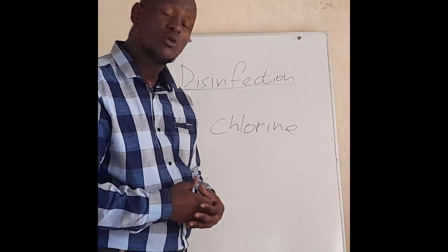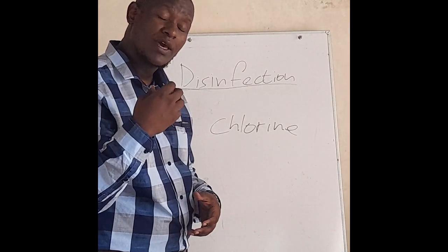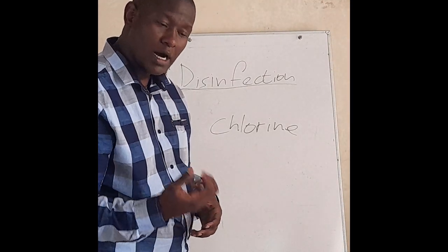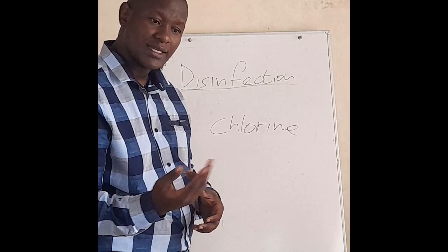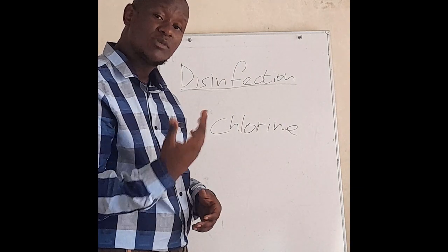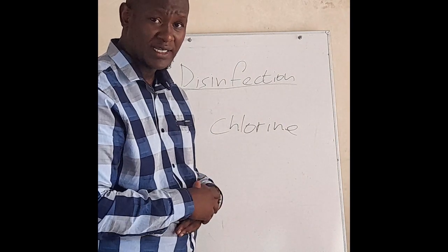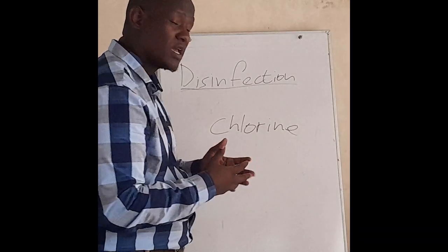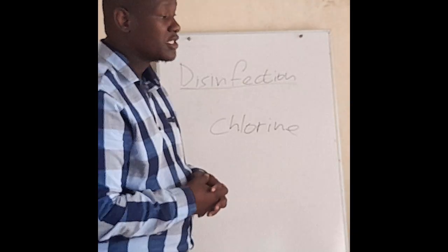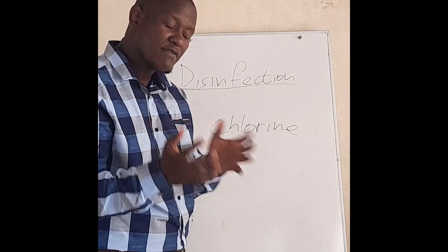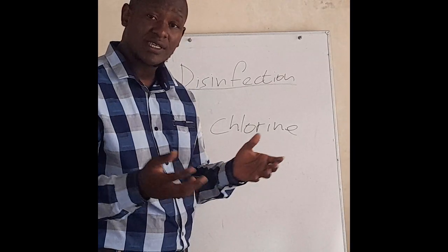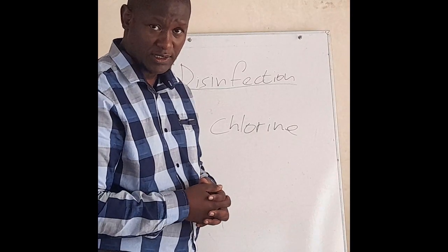Hence it's also important to look at chlorine residual. How do we look at chlorine residual? There are two tests that are normally done. For instance, there's the DPD test and the orthotolidine test, which are very accurate, that you can use to look at how much chlorine is still left. Do you still have any chlorine left when the water gets to you at home, for instance?